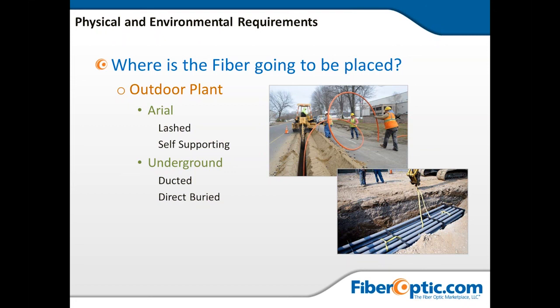So these are questions and considerations for you to think about. Again, this is about asking the right questions. Now, if you're going underground, are you going to be ducted or are you going to direct bury? I will tell you my preference is almost always to put it in duct. My preference is always to put in about 4 times the number of pipes I think I'm going to need.